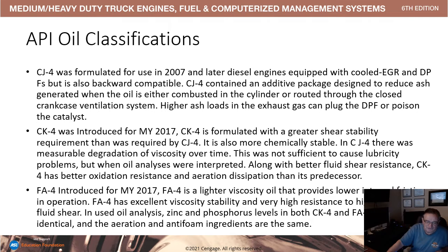CK-4 was introduced in model year 2017 for greater shear stability, along with better oxidation resistance. And FA-4 was also introduced in 2017, a lighter viscosity oil with lower friction operation. These are generally used in engines that do not use a gear pump but use constant velocity oil pumps.